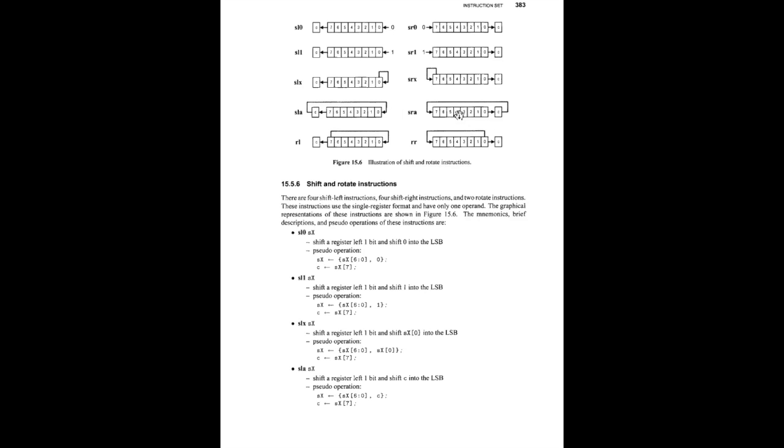Shift right all, again. Rotate left, we're rotating the 16 bits in our register with the MSB getting dropped into the carry bit. Rotate right, same thing with the LSB getting dropped into the carry bit.